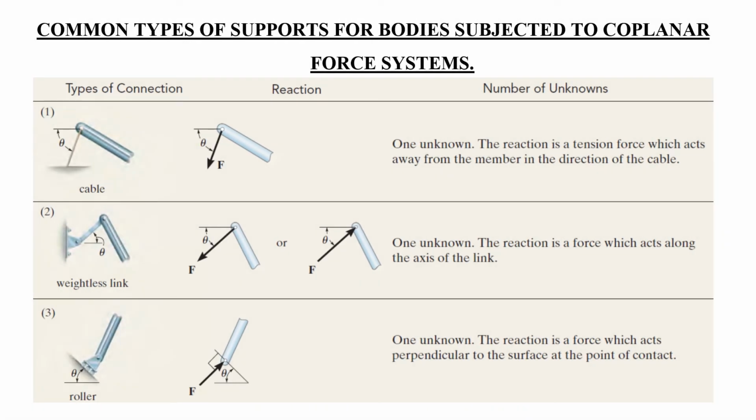So where that brings us is the common supports and how we can represent those in terms of forces, right? Our objective was to define different bodies and different supports as a free body diagram. We want to remove the physically installed forces. For example, we want to replace this cable with a force, or we want to replace this link with, again, a force.